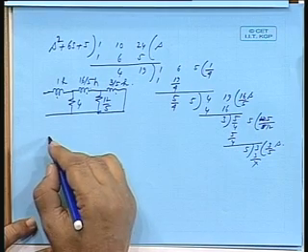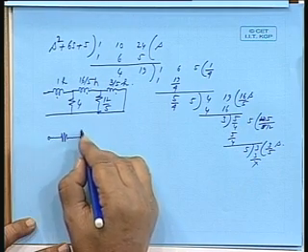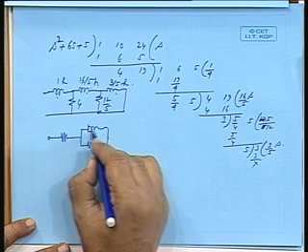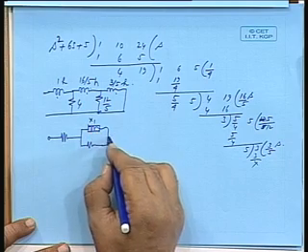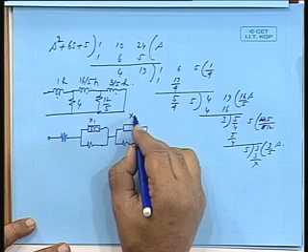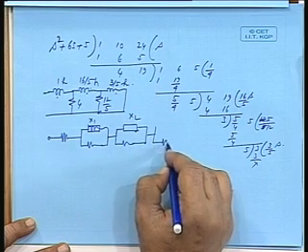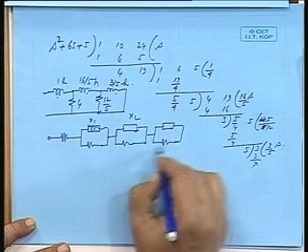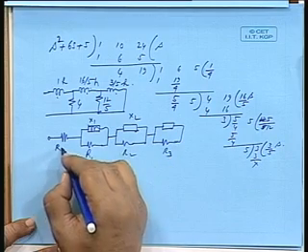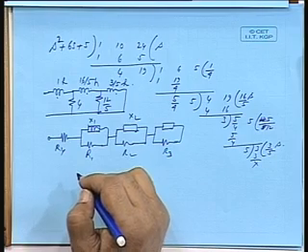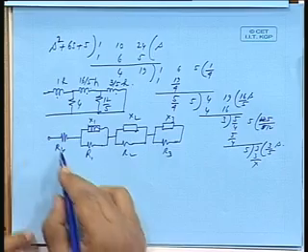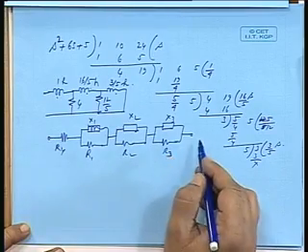The same function you are also asked to evaluate the impedances x1, once again nature and the values of x1, x2, x3, okay, R1, R2, R3, and this is R4. What will be the values of x1, x2, x3? So, obviously, this is a Foster 1 realization.